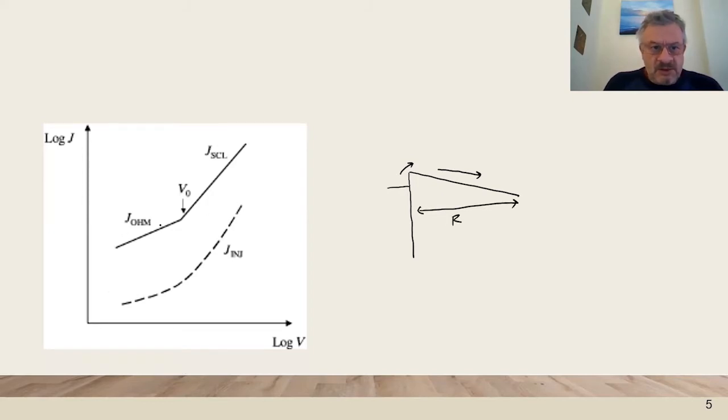This can be ohmic transport. At higher bias, it can go into space charge limited current, for example. When the initial carrier density is exhausted, you need to sustain more charge to increase the current. But there is also, this is the transport resistance, and there is also an interfacial charge transfer resistance at the contact.